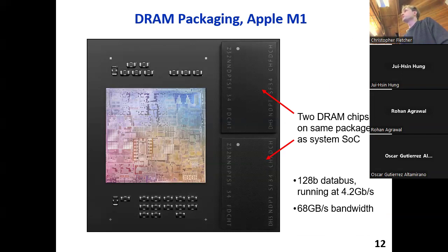That is a good question. So there's actually three actors here. There's the CPU, there's the DRAM controller, and there's the DRAM DIMMs themselves. The DRAM DIMMs, interestingly, are mostly passive devices. There's no internal logic inside the DRAM DIMMs orchestrating things.